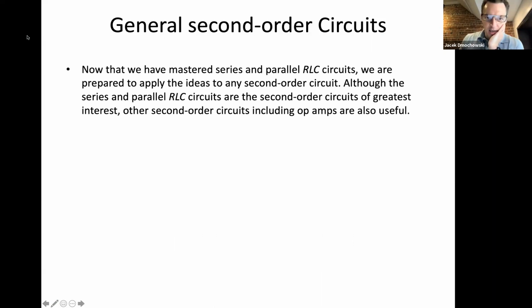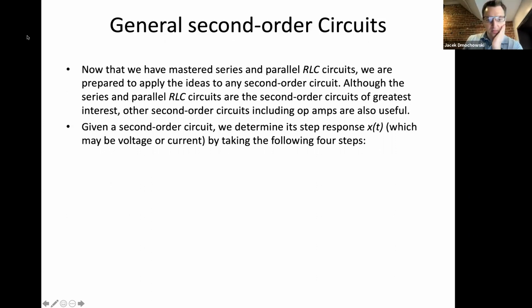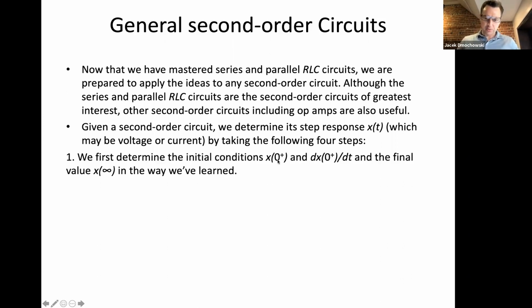The good news is that you can basically follow the prescription that we have been taking to date with step responses. Assume that the circuit quantity that you're solving for is called X, obviously a function of time. That's usually going to be capacitor voltage or an inductor current. The first thing you do is, as before, solve the circuit at 3 separate time points: time 0 minus, time 0 plus, and time equals infinity.